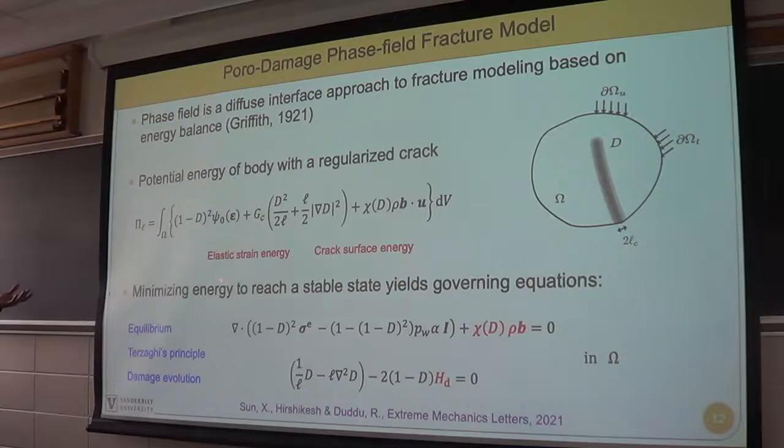And so when you minimize this energy with respect to two variables, the displacement corresponding to the deformation and the damage corresponding to the fracture field, you get two equations. One of those equations is familiar to most mechanicians, which is just your equilibrium equation.